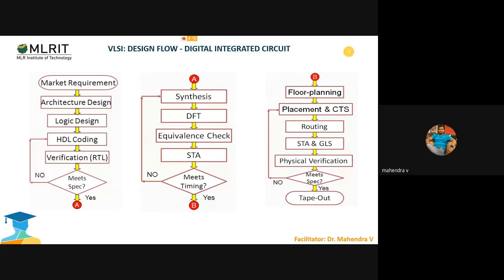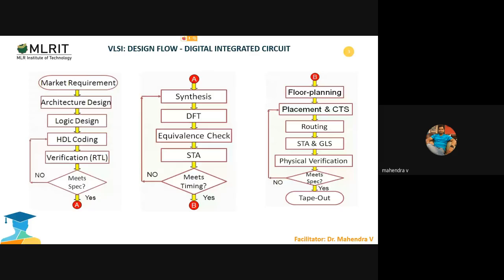After checking the equivalence, here equivalence means at the time of HDL coding one simulation was done. During the DFT one more verification will be done, and if both are matched and all the gates are properly aligned, then we can say the equivalence check is done successfully. Then we verify the timing analysis. That is what STA stands for, static timing analysis. After verifying the gate level netlist functionality, again we see whether it is meeting the timing requirement or not.